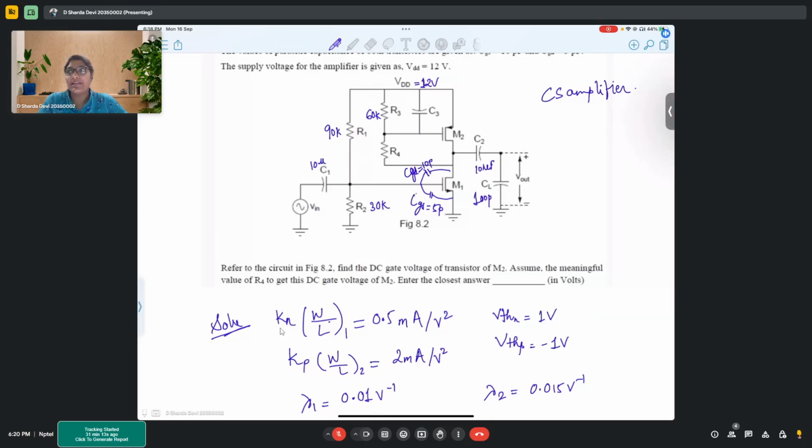So when you want very large resistances, say in mega ohm or giga ohm range, you can use, I guess, the oxide resistance that will come from your device. The gate side would give a capacitance, which is undesirable if it starts conducting current, so that's where I'm saying.